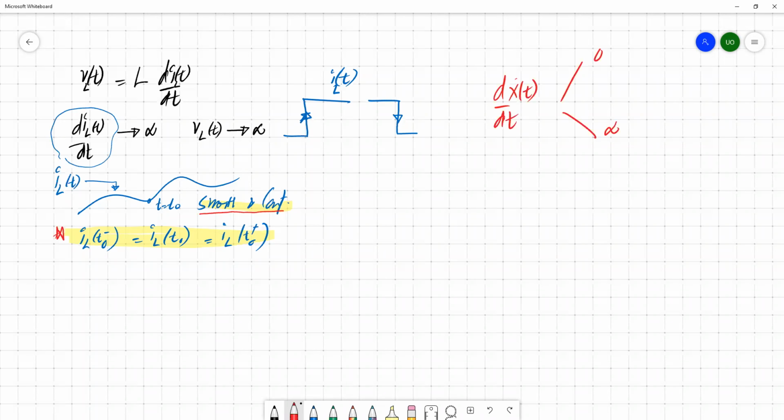Once it goes to zero, we found that the induced voltage or current becomes zero. Based on that, we replace the capacitor and inductor using open circuit and short circuit elements when they are in a DC circuit, in the DC domain. Once the derivative goes to infinity, the induced voltage or current would simply jump to infinity.